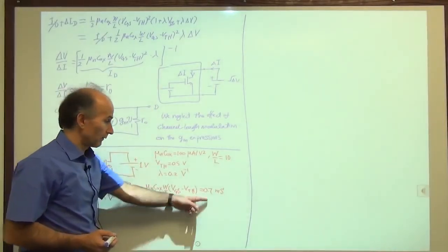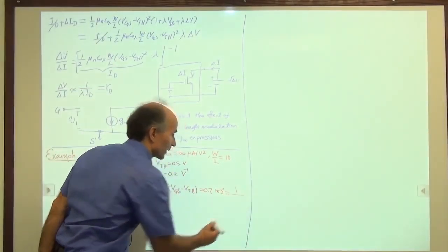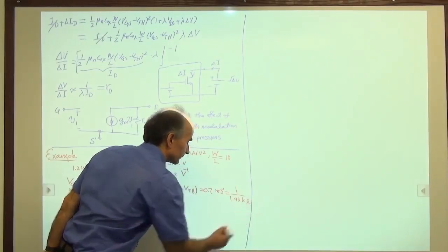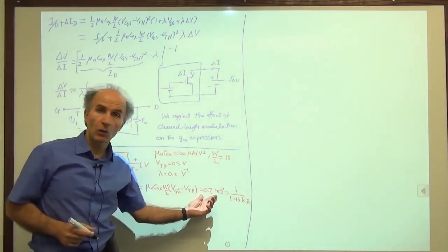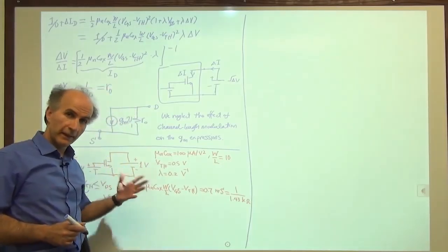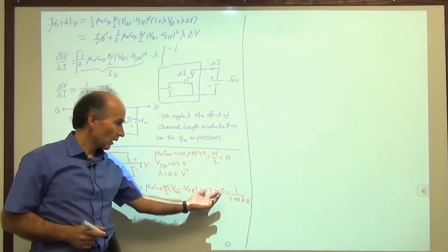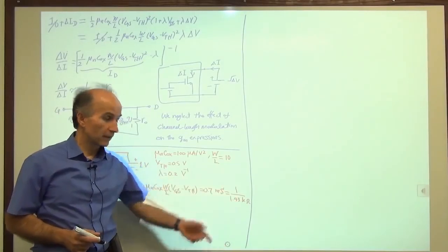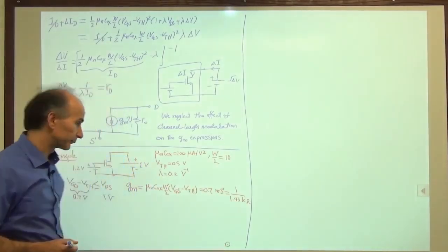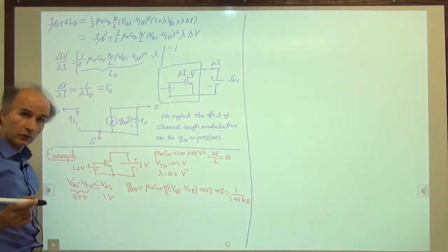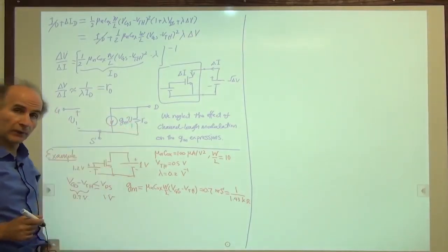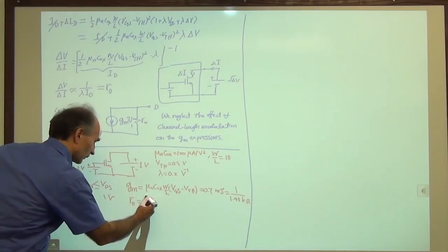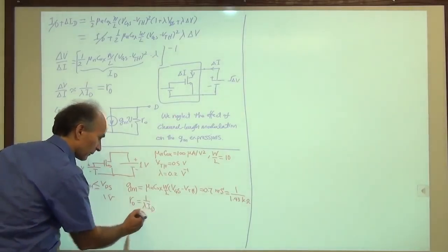And you can also just invert this and write in terms of ohms. So we get 1 over gm is 1.43 kilo ohms. This is a relatively low transconductance for a MOSFET. Typically, in our designs, the transconductances will be higher than this, or this resistance will be lower. So we are looking for maybe a resistance of a few hundred ohms. So that's the typical value. All right. Okay, so we found gm. Good. That's done. Now we go to ro. ro was 1 over lambda ID. So ro is equal to 1 over lambda ID. ID is the bias current.